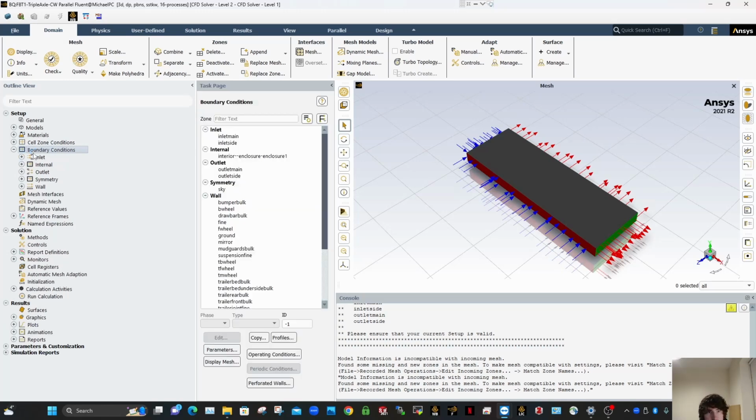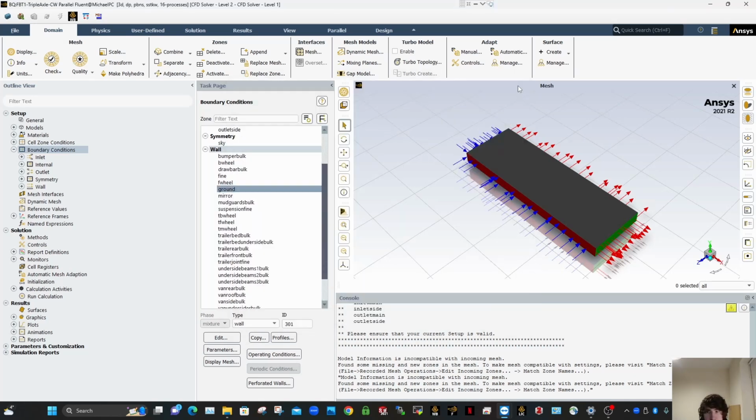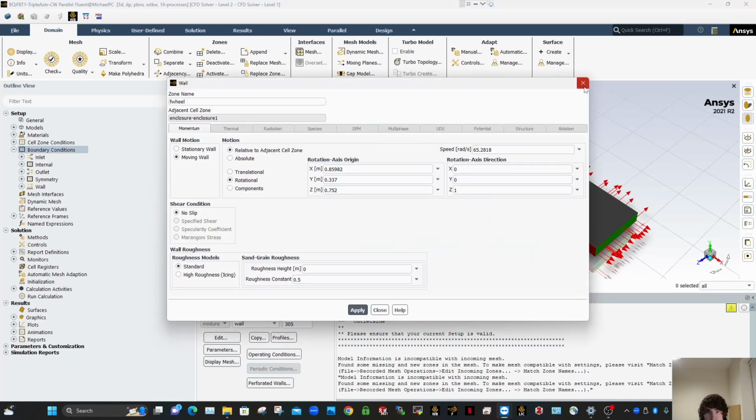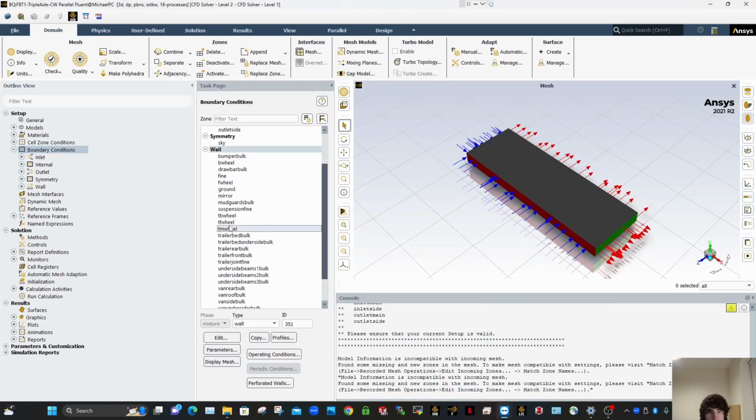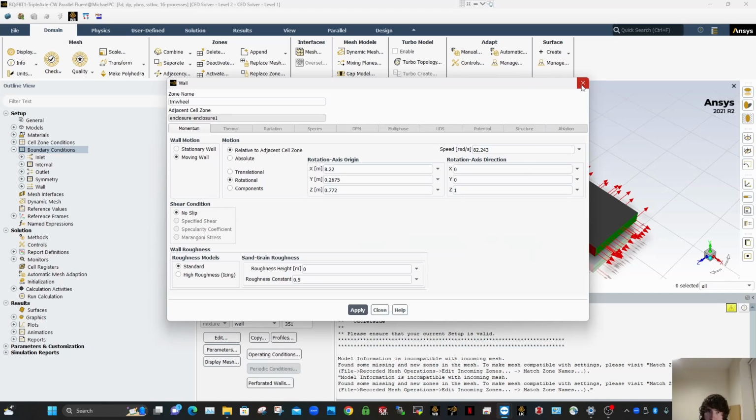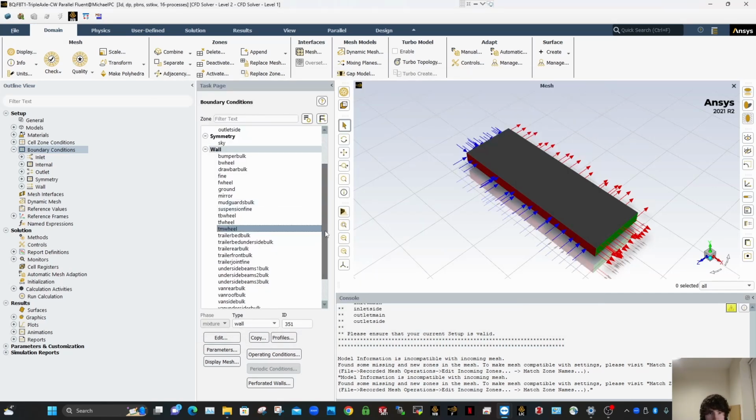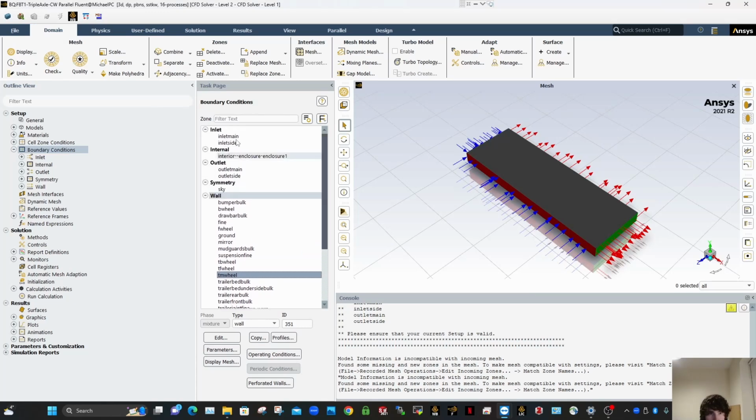And now the boundary conditions, this is the most important part here. You need to get this right. So thankfully, the ground will still be moving at 22 in the X direction, and my wheels will remember the settings that I put on them for when they were in the sort of direct oncoming flow. That's because I duplicated this mesh block, this Fluent block. So they're all grand. So what will need fixing is the inlets.